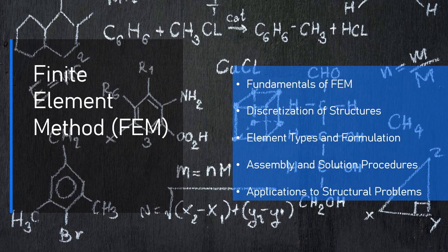5. Apply external load. Apply the point load at the free end in the global force vector. 6. Solve for nodal displacements. Solve the system of linear equations for the unknown nodal displacements. 7. Calculate internal forces. Using the calculated displacements, compute the internal forces, e.g., bending moments, shear forces. 8. Post-process the results. Visualize the displacement of the beam and check the stress distribution to ensure the design meets safety requirements.